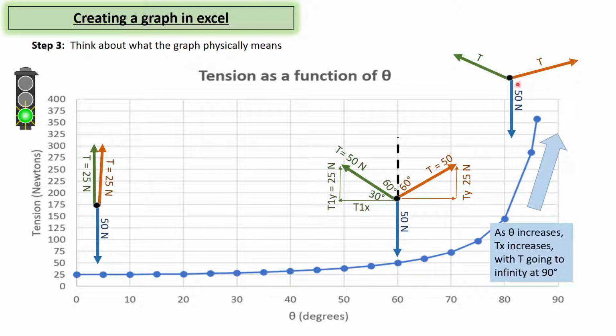If you have a tug-of-war with someone over a situation like this where you're holding up a weight, you can put this on trucks or whatever you want to try and stretch it apart. You will never get a nice straight cable across. And it really is a tug-of-war game. As you increase what's in the x direction and increase this, you'll always need that little chunk in the y direction to hold up your weight.